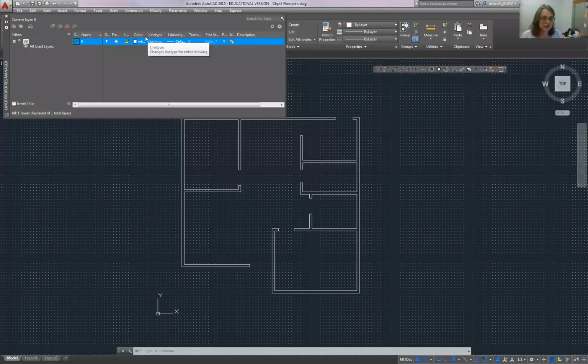So for example, there are conventions around electrical lines, and what line is in a drawing indicates a certain type of line that you will run in the wall. And so you can put all of that on a layer and be in compliance with that convention, and then you can change that line type all at once for everything on that layer.